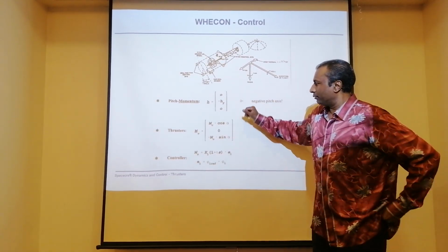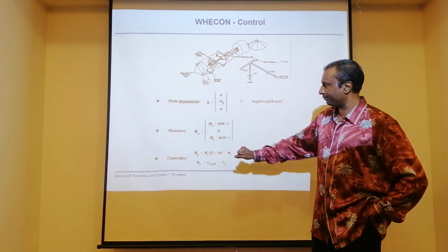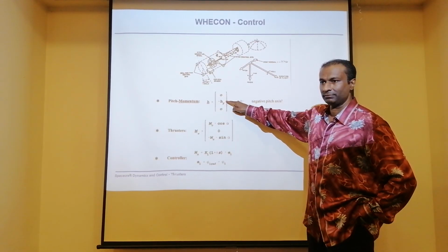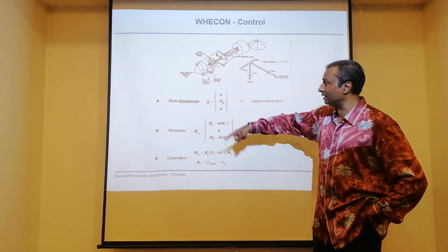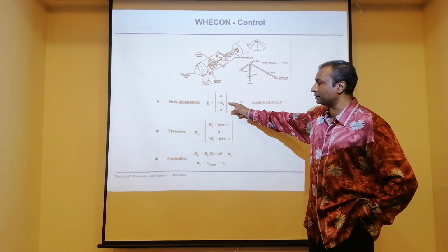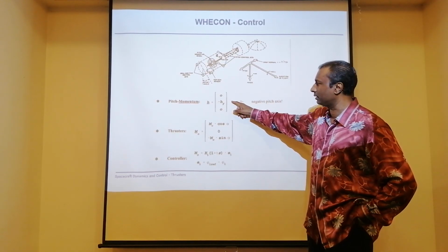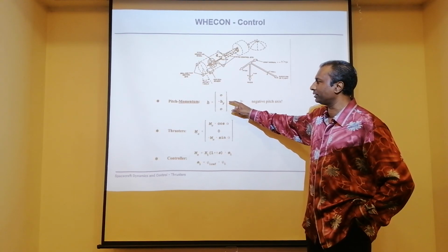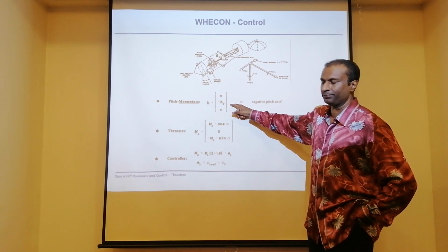So, what it says is that, look, in order for me to have 3-axis control, I have pitch momentum taking care and giving me a gyroscopic stiffness, just like in my previous chapter. Plus, when I have a pitch angular momentum wheel, I should also be able to take care of the pitch axis attitude. Done.